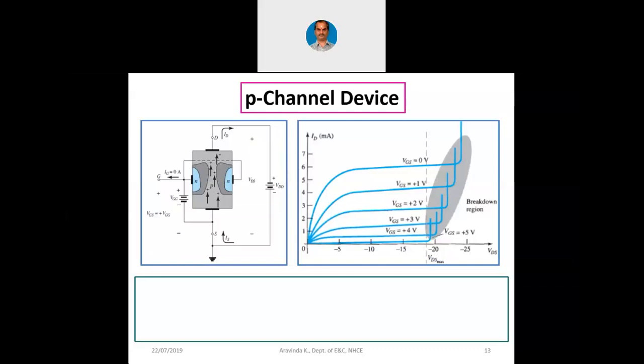So in general, I had shown you the data sheets in the earlier module. I had discussed in brief about the data sheets, and there I had told that if in our power supply, if in our circuitry, let us say a device has to handle 10 volts, we will choose a device which is capable of handling 20 volts, which means that we will always select a device which is double the rating of our application.